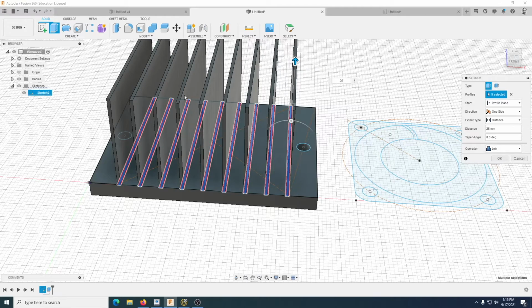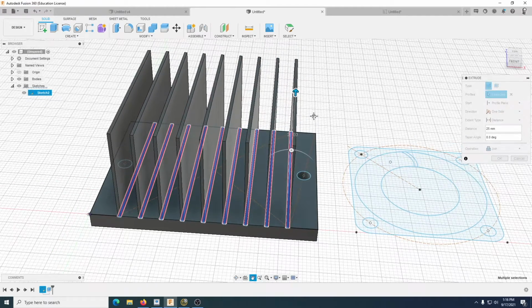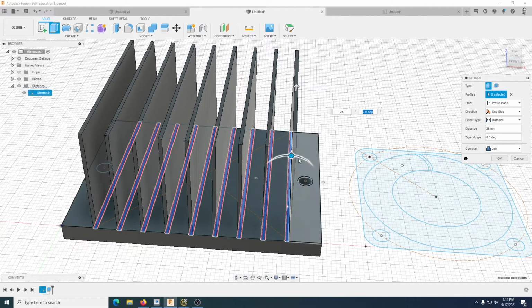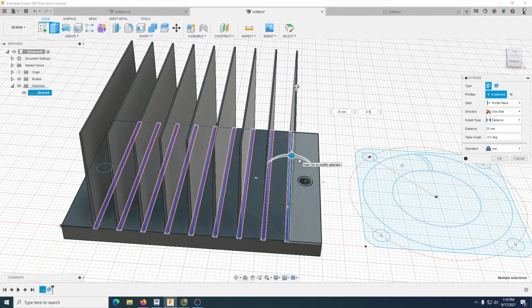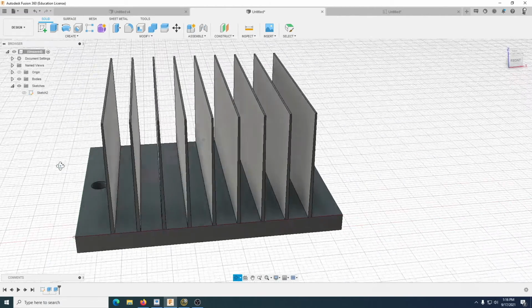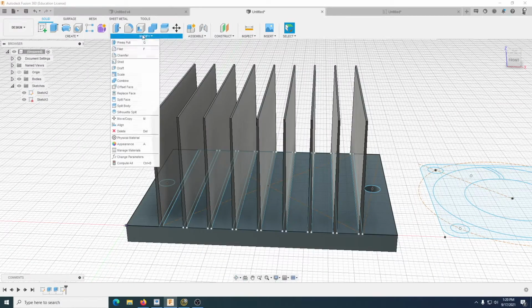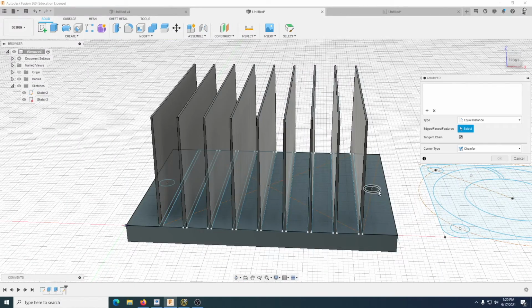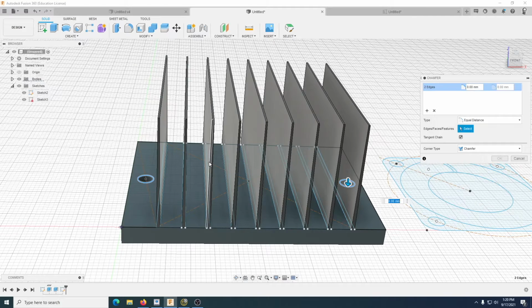Now we know that the fins actually get a little bit tighter, so there's no reason why you can't do that. We can just click this, but I wouldn't do it too much. We're looking at a minus. You can do a 0.5, actually it looks a bit better. And everything's joining. If I turn the sketches off, things become a little bit clearer. So we will just go to modify, chamfer, click that edge, and just put 1.5 in.